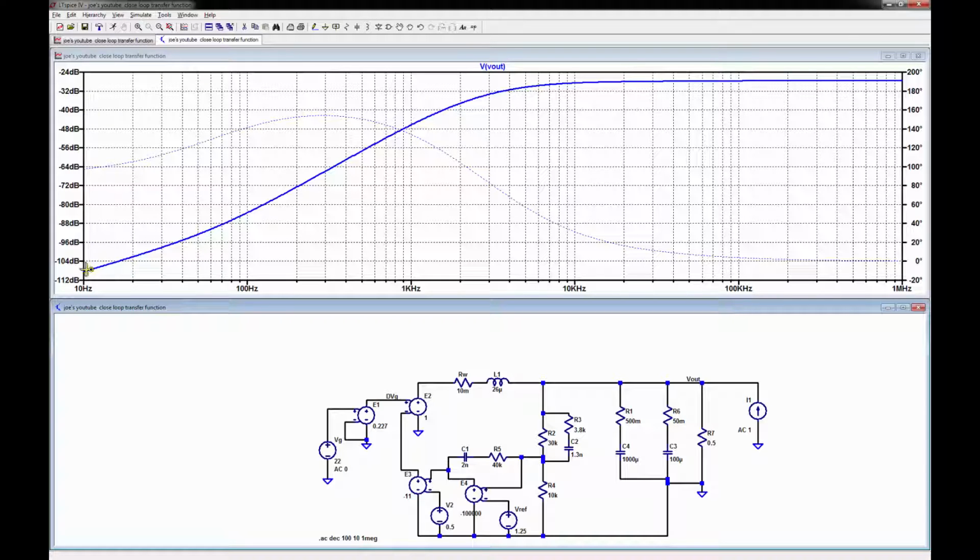It pulled it down to what? Our loop gain. 1 over 1 plus T, which means T is much greater than 1, so it's pretty much 1 over T. So if this loop gain bandwidth was 60 dB, it would be 60 plus the 30, which is this. So this is what we have. This is pretty cool. We have just done everything, including open and closed loop transfer functions. Hopefully this will clear everything up.